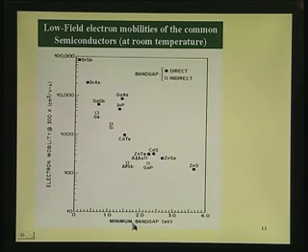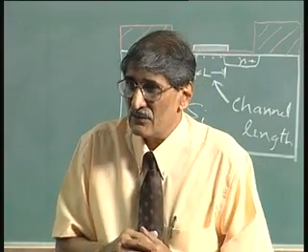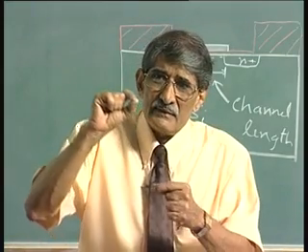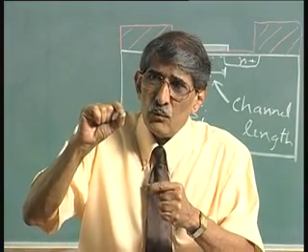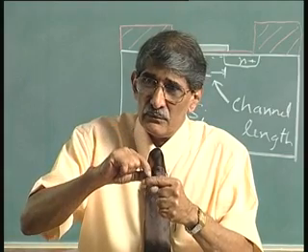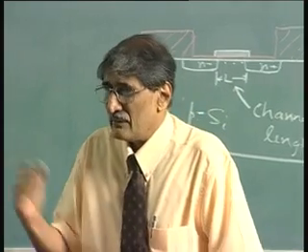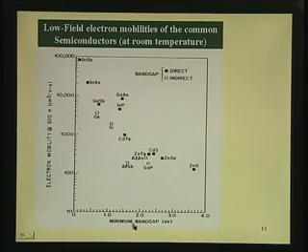Just now you took it as a band gap. It is actually a band gap that varies in certain directions. So, we are taking the minimum value of the band gap. That is, if there is an electron at the conduction band, what is the energy it must lose to go to the valence band? That is the minimum energy. So, that is what is meant by, conventionally, just saying band gap, energy band gap. So, that is put here.